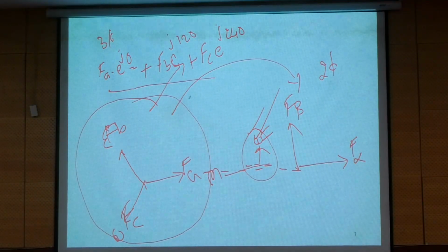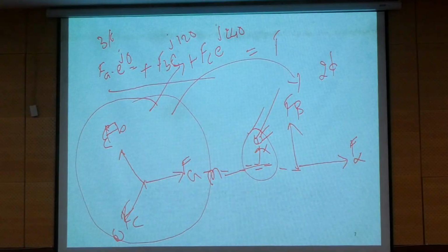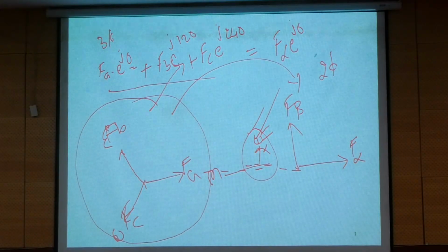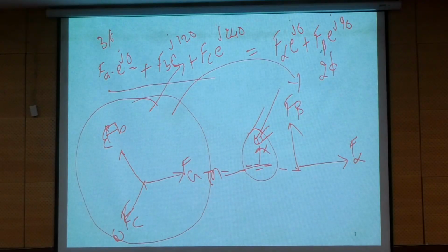So this is the mathematical model: the resultant MMF produced by the three-phase system with respect to this phasor. And with respect to this phasor, what is F alpha? F alpha into e power j0 plus F beta e power j90. Solve this equation first. Tell me what the real components are and what the imaginary components are. Here, FA, FB, FC are known values. Please try to understand: FA, FB, FC are known values, and F alpha and F beta are unknown values.